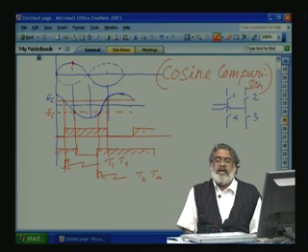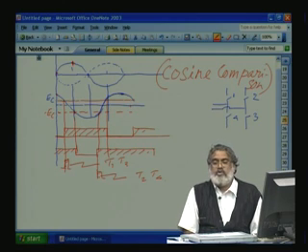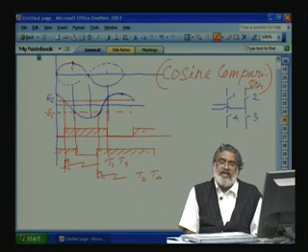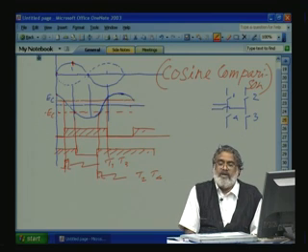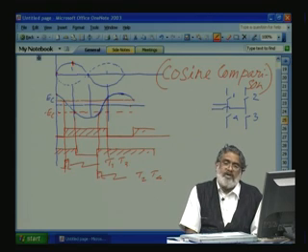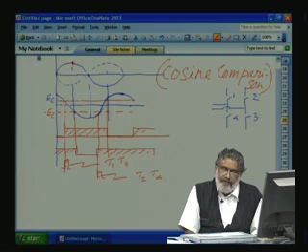Also, how we can have a converter with 4-quadrant operation, that is a dual converter, and the circulating current to take care of the ripple voltage level, we have talked about it. Then we also studied that the front end converter has a power factor problem. Then we studied how we can control the front end phase control converter as semi converters. We have studied this portion also.